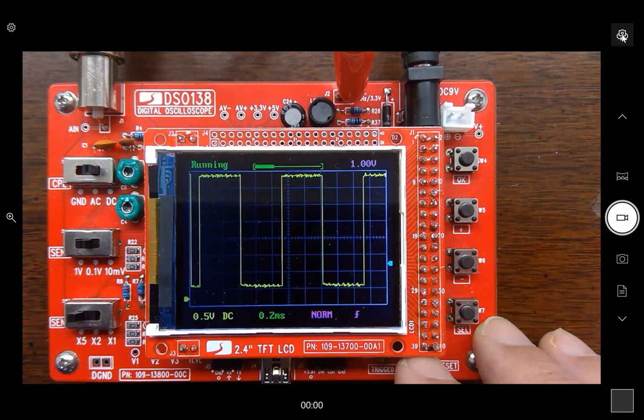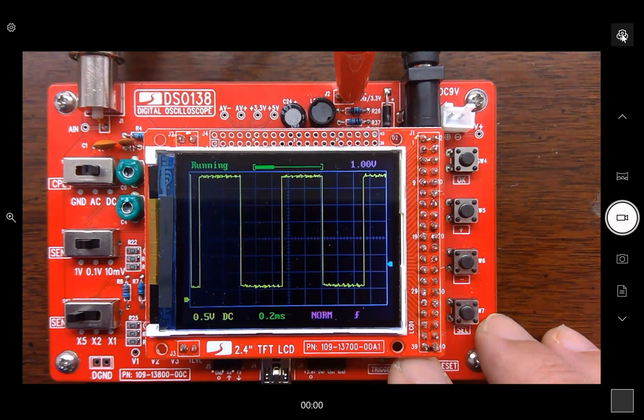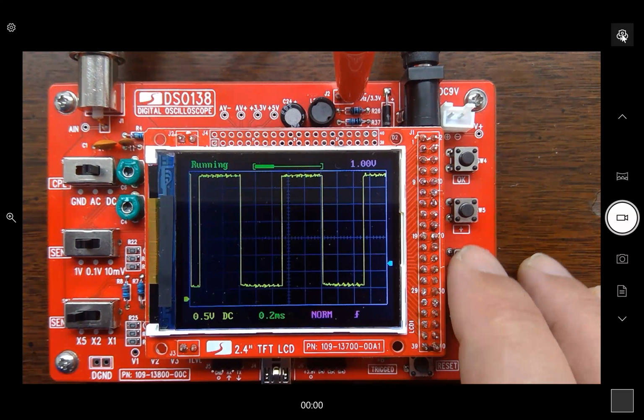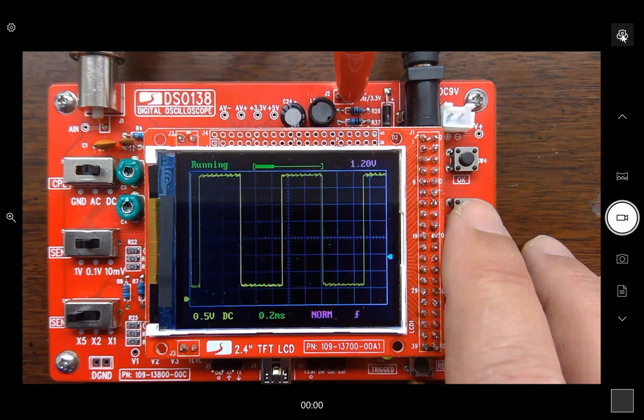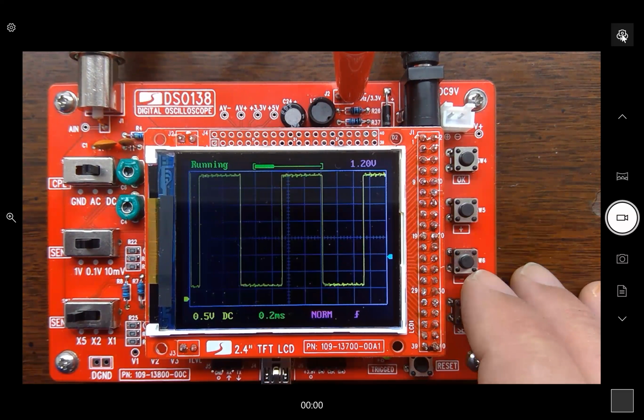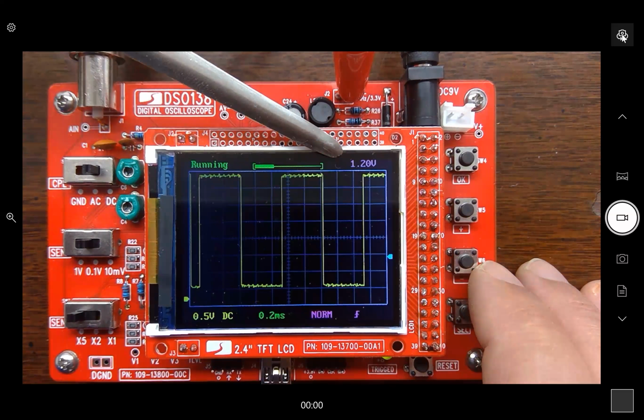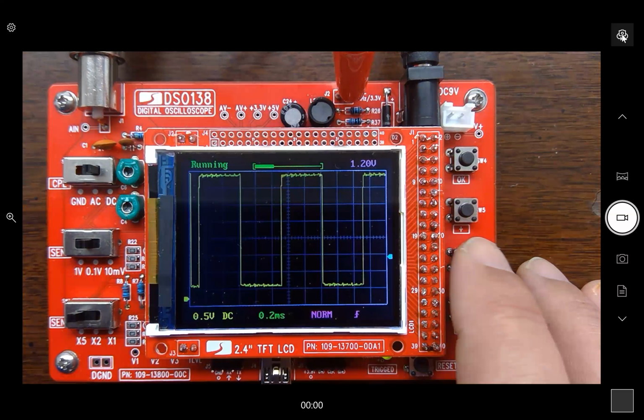And it doesn't want to play. That's one of the quirks on this oscilloscope, is sometimes it doesn't want to play nice, and maybe I just didn't go far enough up. There we go. Yeah, I just need to go a little bit farther. Okay, so now it's triggering normally again. And again, the actual trigger level right now is 1.2 volts.